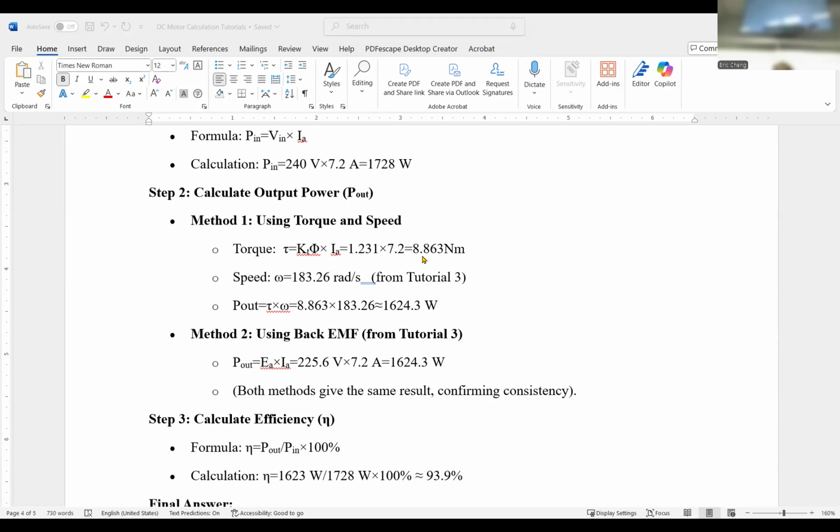Like when a motor stalls, that means it suddenly stops, then we don't have back EMF. If the motor doesn't rotate, we have a problem. The motor will get really hot, and that's the thing we don't quite like. From this equation, you can see that the motor current can be really large. If you calculate losses, 250 amps squared multiplied by R, that will be really high power losses, so that cannot last for a long time. We should allow the motor to continue to go up in speed, then the back EMF will come in, and then you can oppose the input voltage.